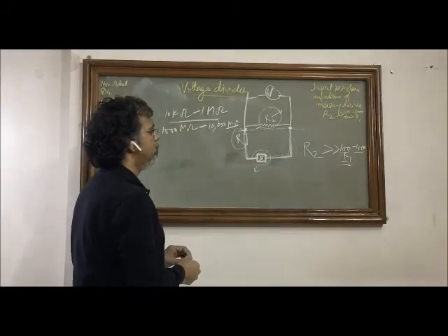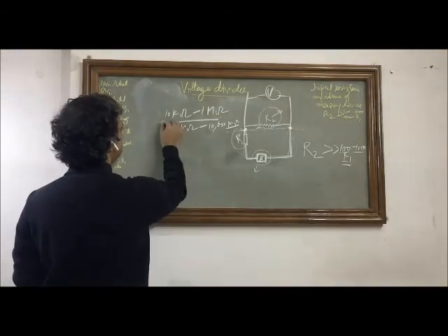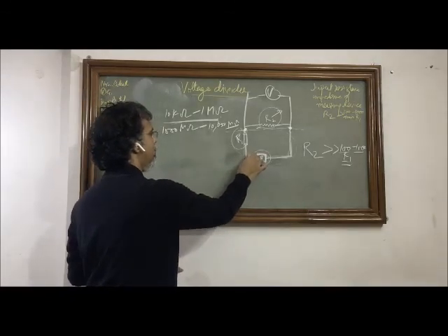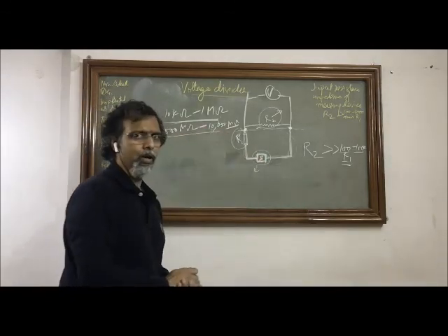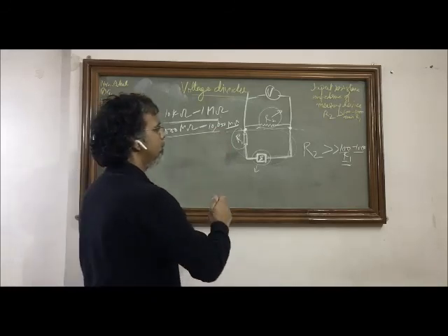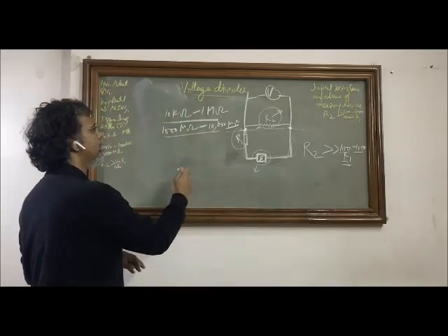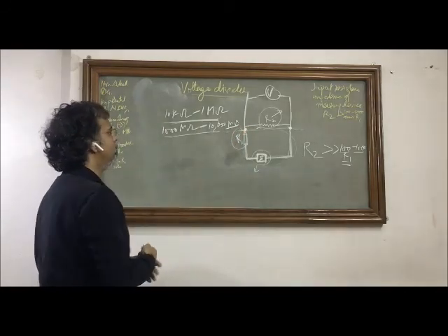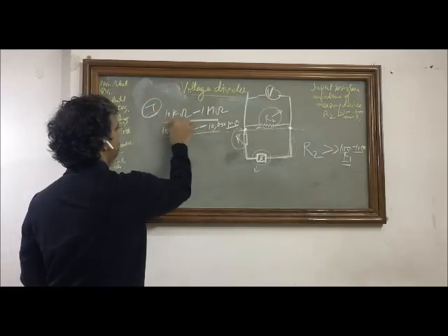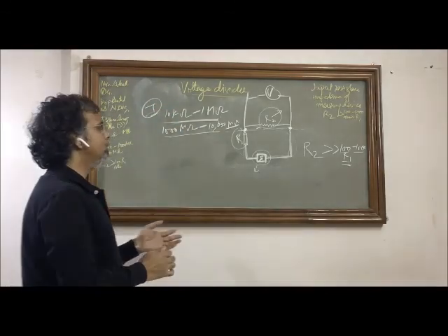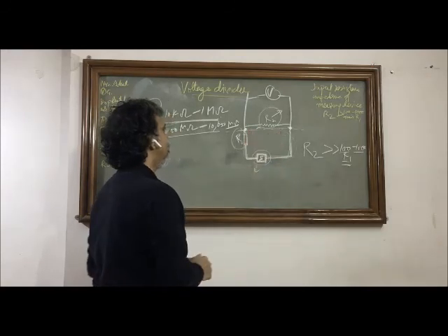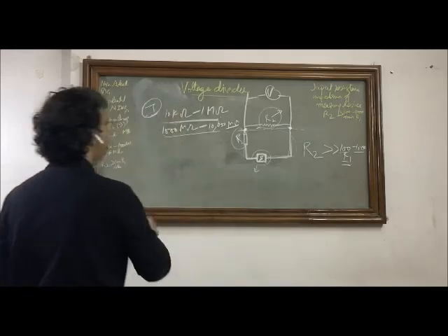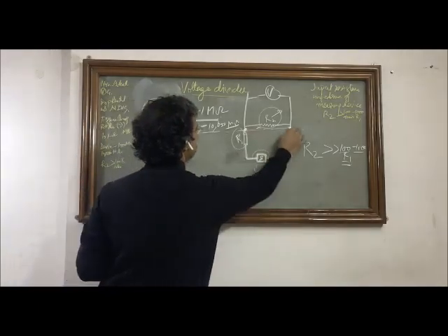The only thing we need to consider is the range or order of the tissue impedance, and we will make our device's internal resistance 100 to 1000 times more than that of the internal tissue impedance. Practically, tissue impedances are in the order of 10 kilo ohm to 1 mega ohm, and normally the measurement device will have an internal resistance from 1000 mega ohm to 10,000 mega ohm, and we can measure the biopotential.